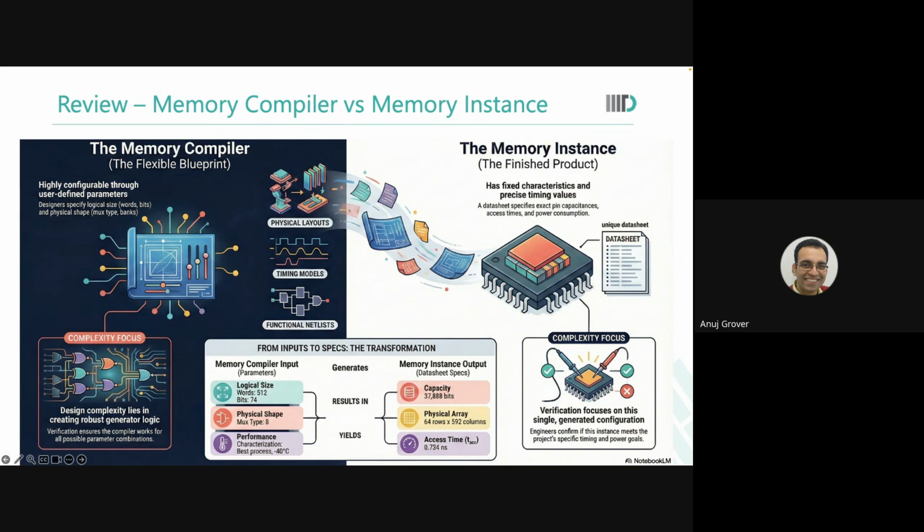Okay? Now, I am teasing you that you did Monte Carlo on power. I will keep teasing you about Monte Carlo on power. But when we did this, we built the whole matrix over load and slope and so on, and we made the characterization more accurate. We still realize that we are leaving margins. Why? For the Monte Carlo variations. Because in reality, on the chip, something would run a little faster and something a little slower.